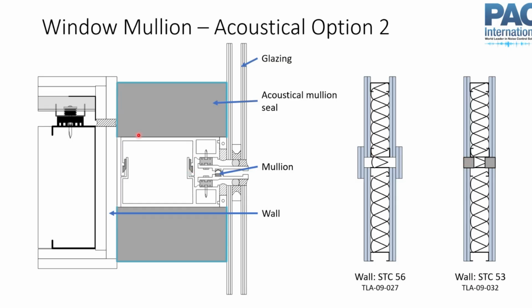But again, as you're doing this, you want to make sure that you don't create some sort of structural transmission path here too, right? If you started attaching this drywall over here, you can see here I've got this gap in this drywall, whereas if this were continuous, that creates a structural transmission path through here. So again, for trying to address one of these, we want to make sure we don't create a new issue with our solution to the first one that we had.